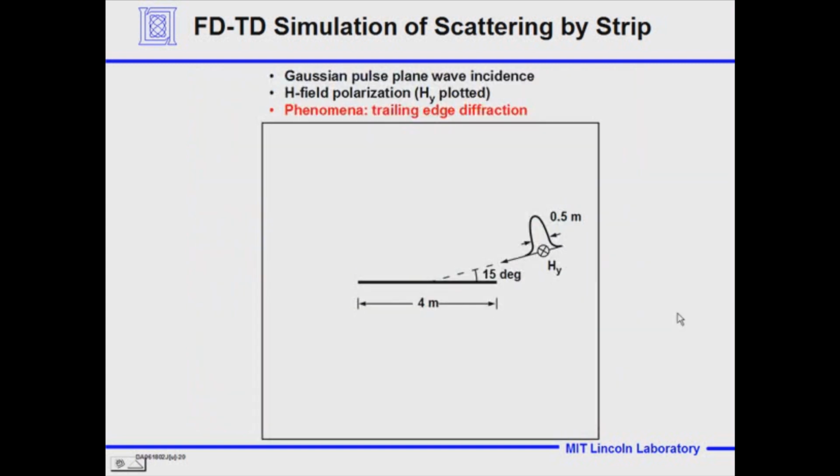To let you know how this is polarization dependent, that's where we had the polarization going in one direction. Now when we change the polarization, we'll get trailing edge diffraction. Now a lot of radars use radiation that's a mixture of linear polarization. What you saw was a radar that was linearly polarized, with the electric field exactly perpendicular to the plane. It was vertically polarized, perfectly relative to the wing surface.